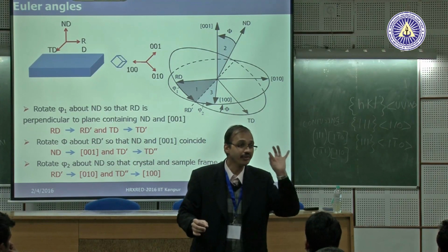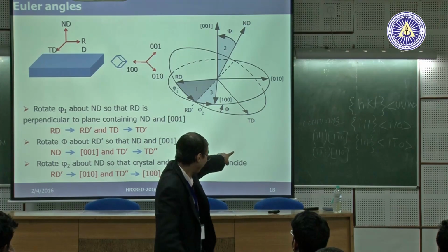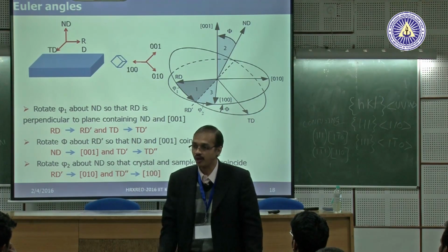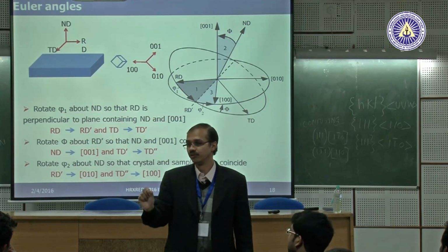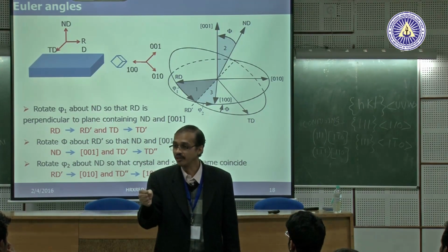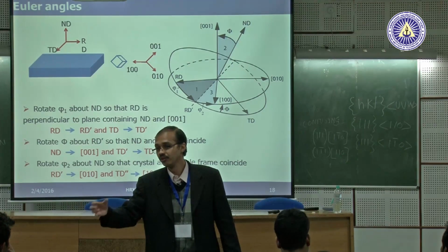Okay, so for each and every orientation, instead of writing HKL, UVW and confusing you with the brackets and then saying that you change the orientation, for all the different orientations you are going to get a distinct phi 1, phi 2. So that is an easier way of storing my information, right? From 9 angles I have come down to only 3 angles.